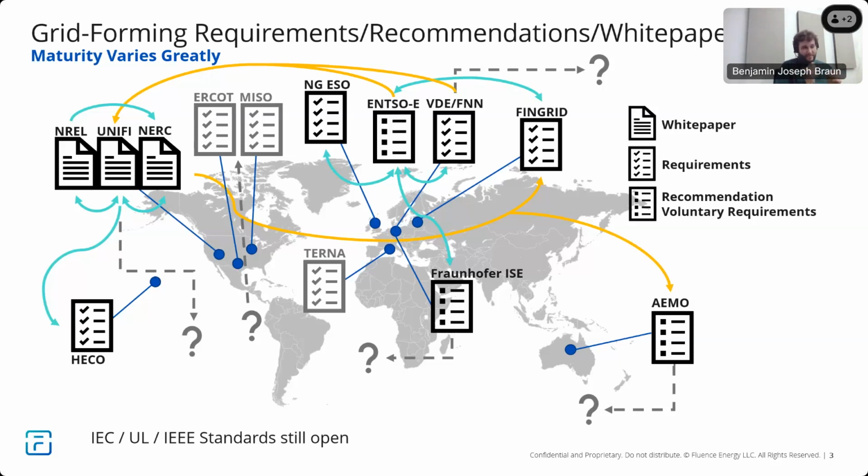There's some very minor mention of maybe standalone inverters or something like that, but it's definitely not to the point where you can, as a solution provider or as a project developer, just go around shopping for inverters or power converters as you would in a grid following project and say, right, I need to see this certification and this one, and if you've got that, then I know you're fit for function. Unfortunately, for grid forming, that does not yet exist.